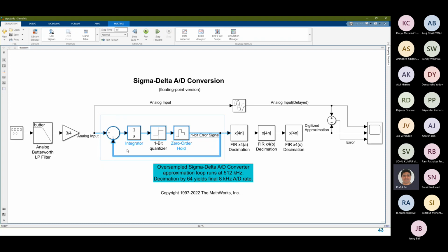What you can do is generate C code from various blocks of this, and then wrap it around a SystemVerilog wrapper, and import it into your Virtuoso or AMS environments. Okay, so again, what you can do is look at creating sub blocks. So something like this.